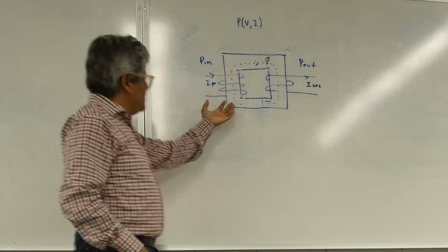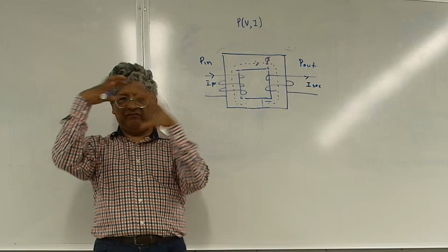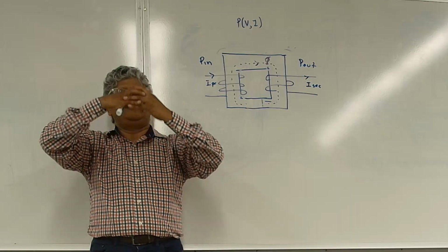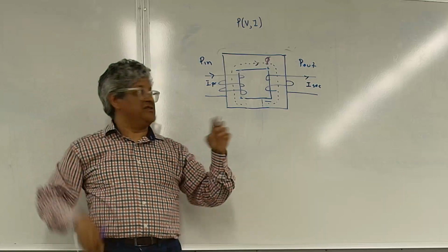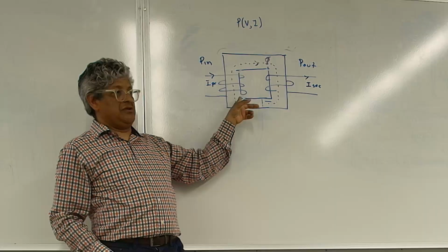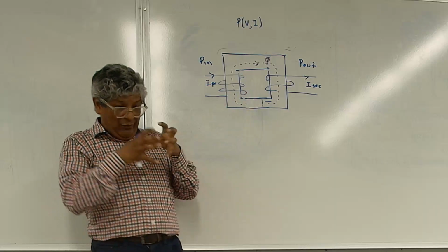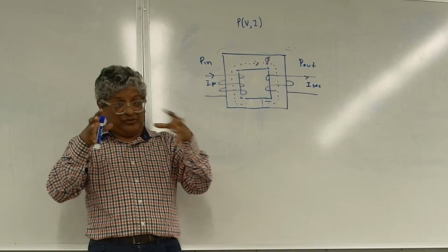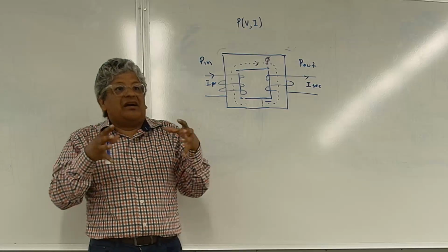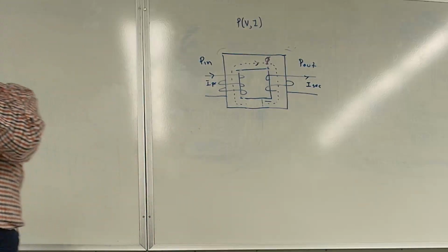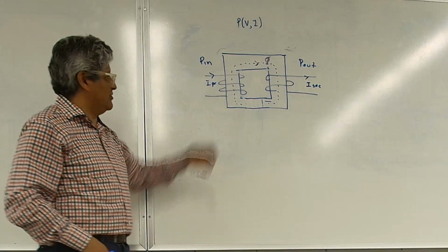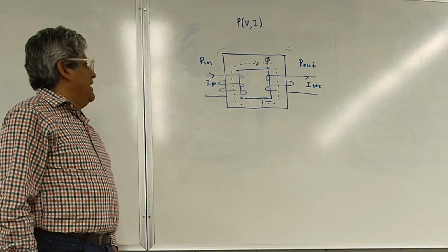What happened is that the geometry, how we had these laminations, was not precisely aligned. They were like this. You can see the edges. There's so much flux that was getting into the air, there were so many losses, and it resulted as vibrations, right? There's a lot of things to be said about it, but the idea, once again, is to maintain a very precise core so that your flux lines are within that.